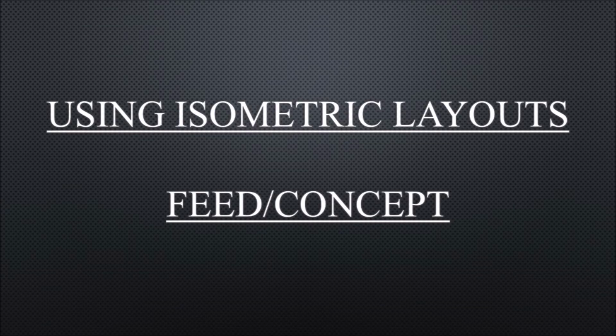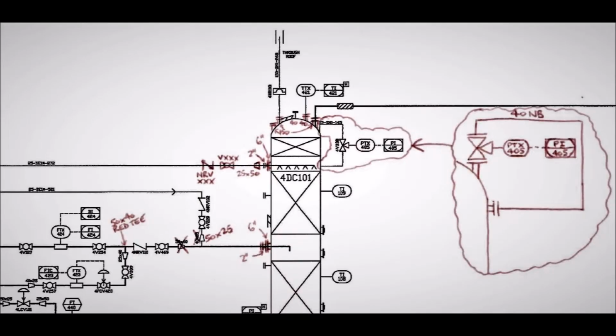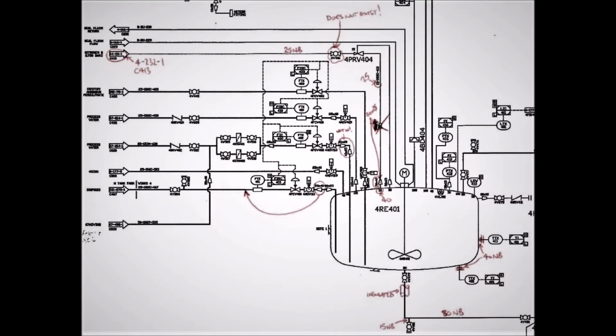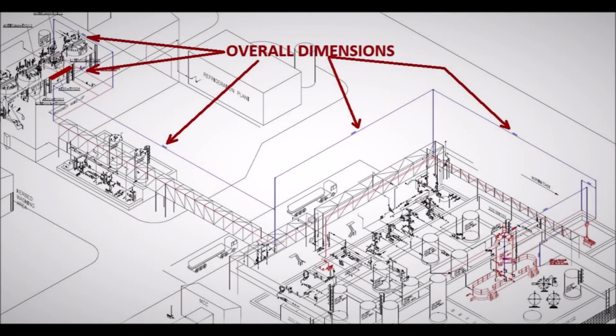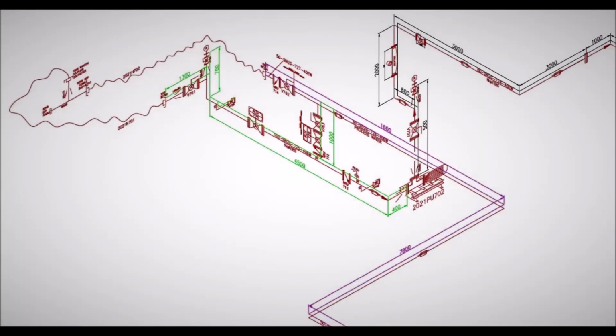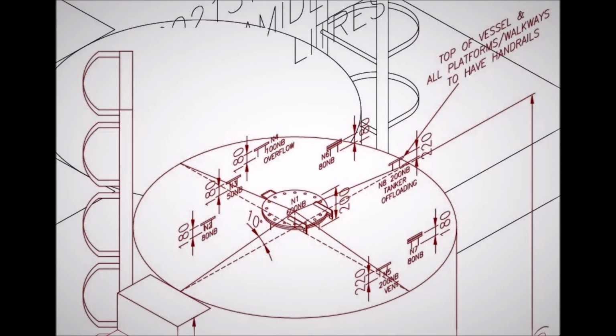Once equipment locations are agreed in concept ISO layouts at FEED stage, they are developed to have further detail as physical layouts result in accurate scope definition for all disciplines. For process, you can have correction of any errors in existing P&IDs, calculations for equipment as height, distances and friction losses are known. For instrument and electrical, cable lengths including heat tracing lengths. Mechanical, layouts show the physical space for access and maintenance tasks.